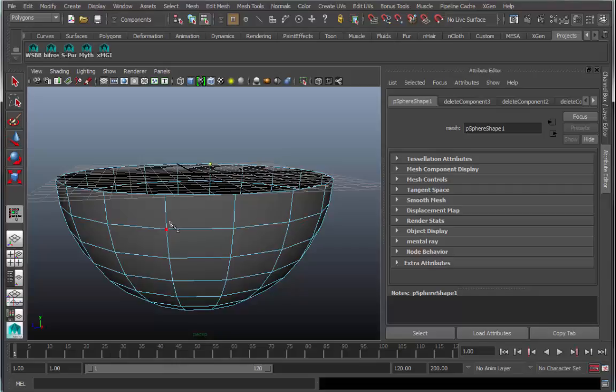Now, you need to make sure you do this before you begin. Hold down the Shift key, because with the Shift key down, you now see the word Snap coming up, and that means that this is going to snap exactly in the middle of an edge. So you're assured a very clean bifurcation of the edge exactly at its midway point. Do not click over here. Make sure you go diligently one edge at a time.